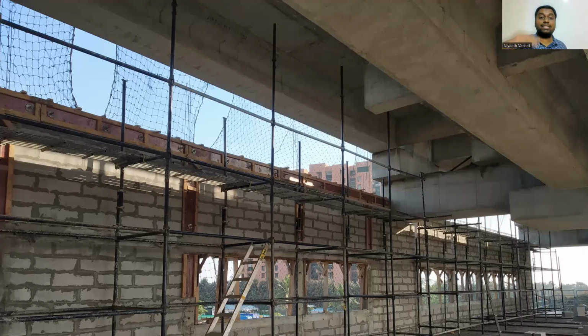So when you have walls at such a high level, you cannot just have columns. You also need to have horizontal beams, and you also need to have something called mullions. So if you look here, you can see that vertical columns have been cast, or at least the shuttering has been done. So these vertical columns are not exactly columns, these are called mullions. These are small scale elements which act like columns, but they are not the structural part of the whole structure. They are the structural part of only the masonry. This concrete structure will help the masonry to stick together because the wall height is very high.